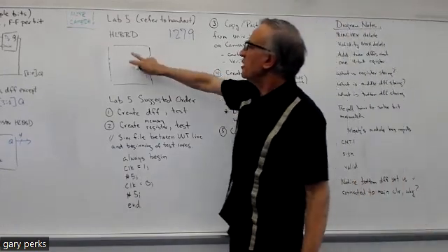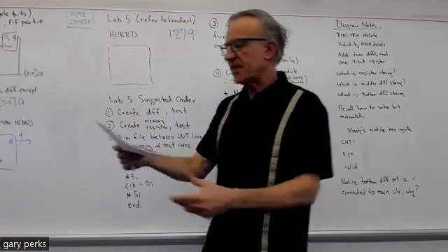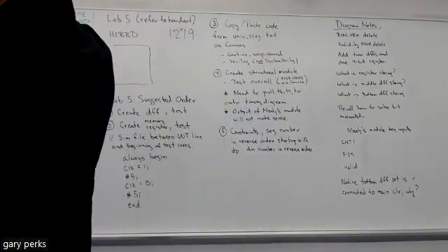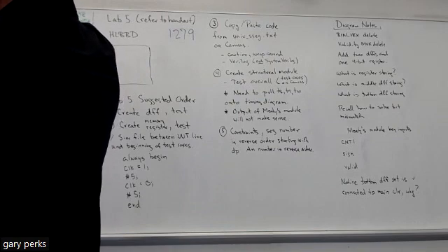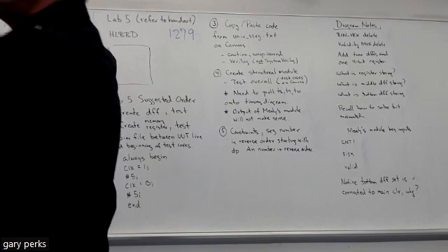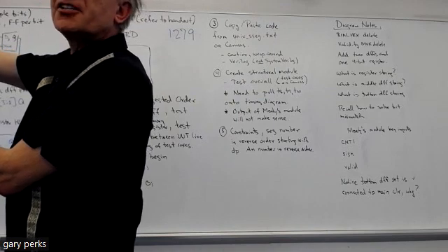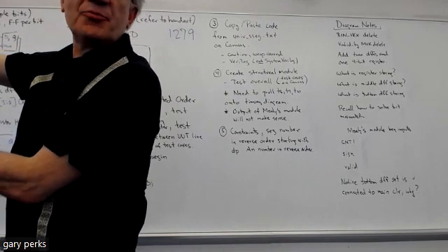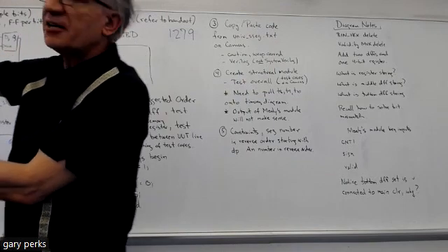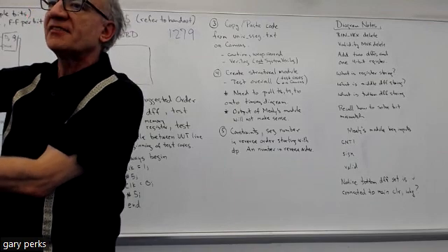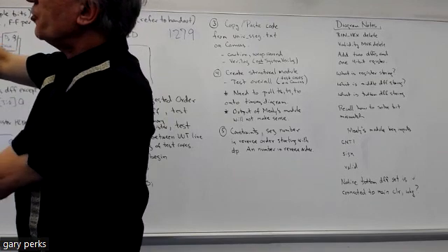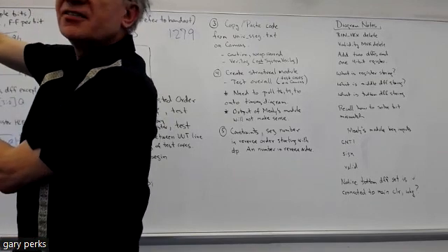Okay, so let's come up with the high-level black box diagram for this lab 5. Okay, so looking at these diagrams here, because notice that lab 5 has a lot of what you did in lab 4, right? This diagram here is the lab 4 diagram. But notice we delete some things. See, in lab 5, you're not going to use the binary to hex decoder. You're not going to use the neg output, and you're not going to use this mux that was being controlled by the validity checker. Okay, so where you see an X, that's all going to be deleted for lab 5. So lab 5 is this portion of lab 4 that's not X'd out, plus what you see here.